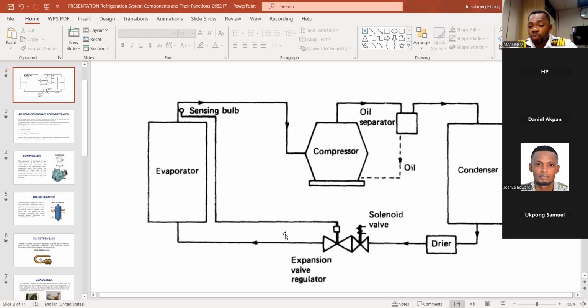The only way for you to check if that capacitor is bad is with your multimeter. Most times it might swell up, or you can see the terminal start leaking. But most times it can still look new while the capacitor is bad. When it looks new, you simply need your multimeter to check if the capacitor is still good or bad, if you know how to use it.